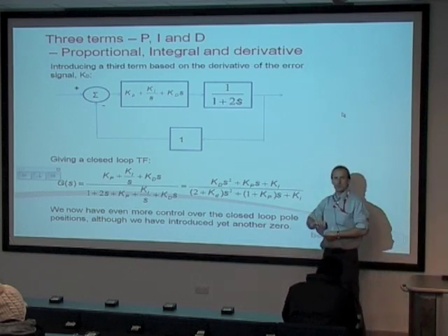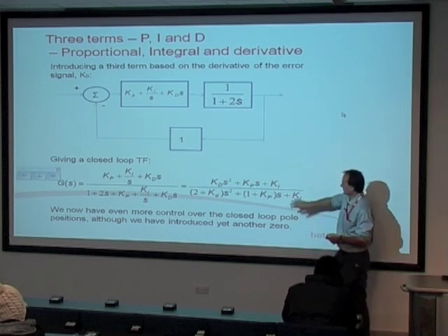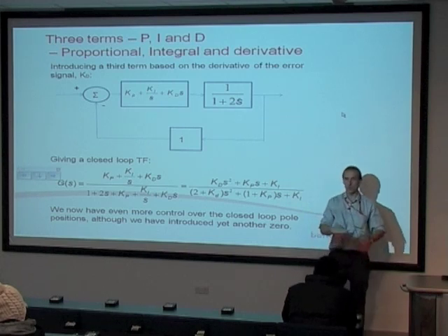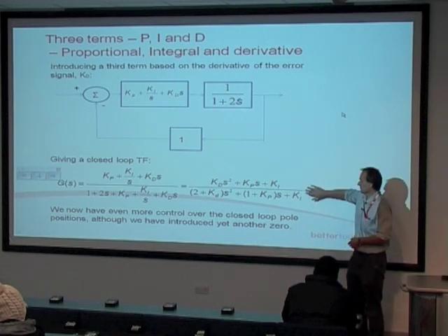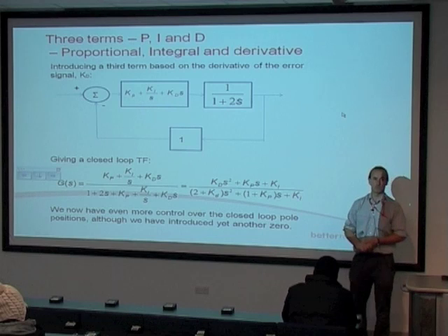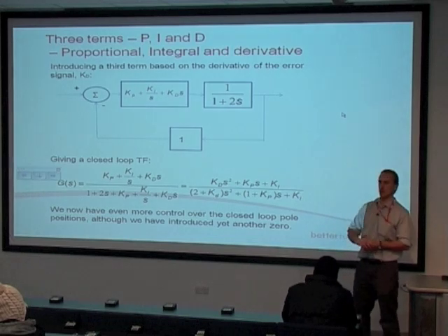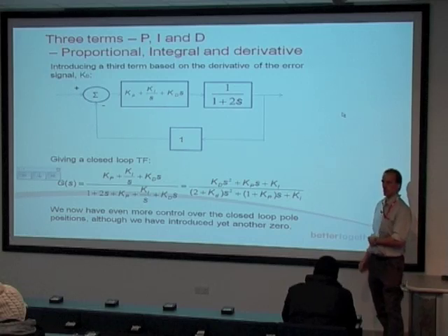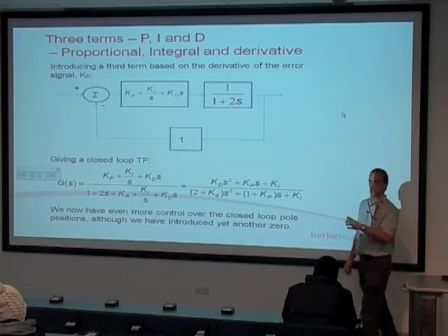Put them into the mix, a three-term controller, off-the-shelf device, look at what happens to your transfer function when you blend it with your particular system, and you get something that looks like that. Again, you'll notice I'm glossing over my issue of having some zeros in the way, and the reason I'm doing that is because I've got a fix.